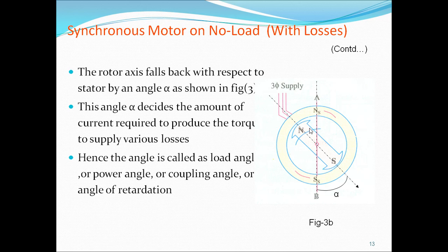So when the load or losses change, the angle also changes such that it develops a torque which supplies the increase in load and increase in losses. This angle alpha is called the load angle or power angle or coupling angle or angle of rotation.